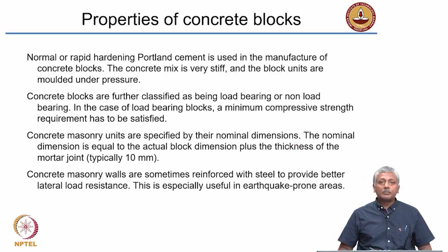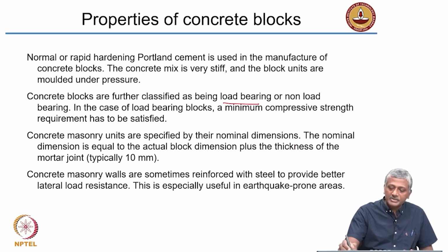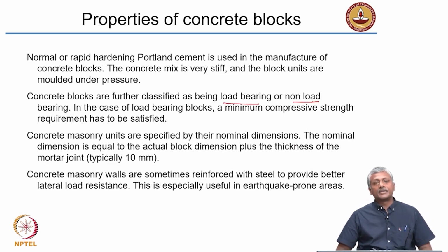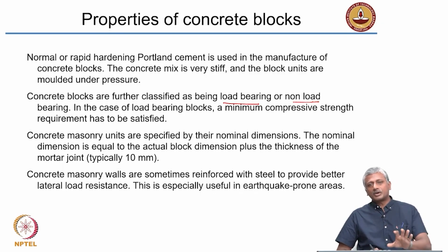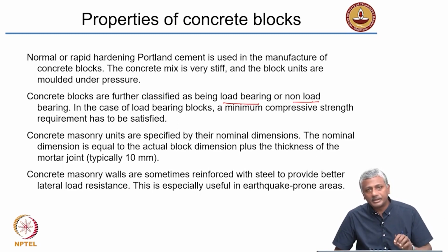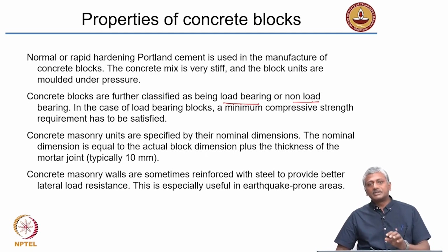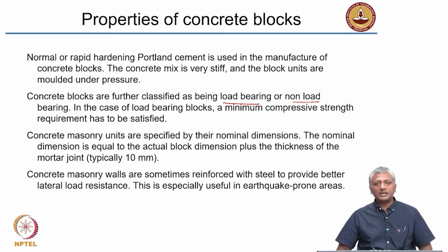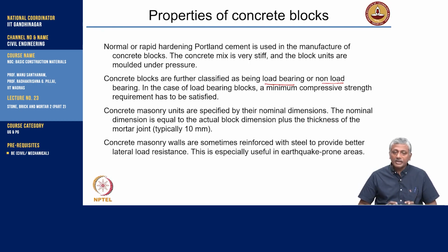Okay. So concrete blocks could be used for load bearing purposes or non-load bearing purposes. When they are used for load bearing purposes, obviously they need to satisfy a certain minimum compressive strength. I have not covered here the IS codes that deal with concrete. I have talked about stone and brick earlier, but with concrete I have not really covered the IS code for blocks here, but you can have some idea about this from reading the content in IS codes. So, you need to have some minimum compressive strength to satisfy the requirement for load bearing masonry.